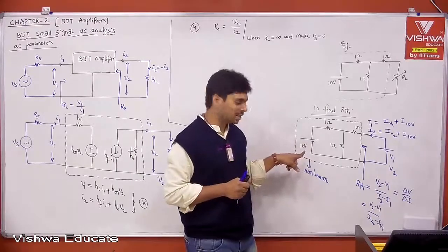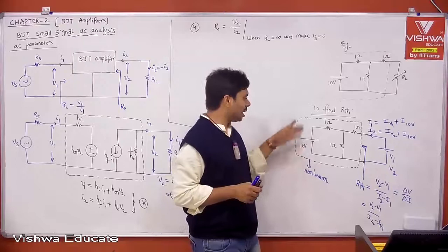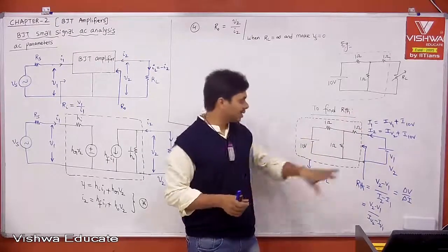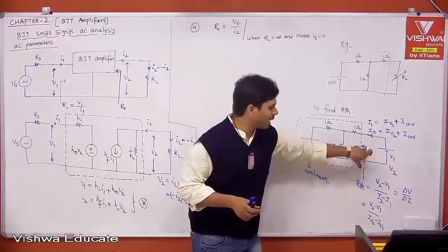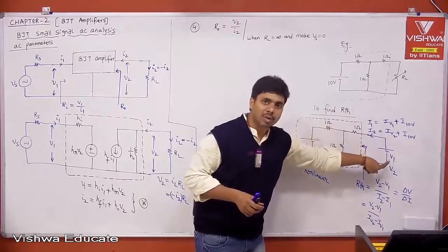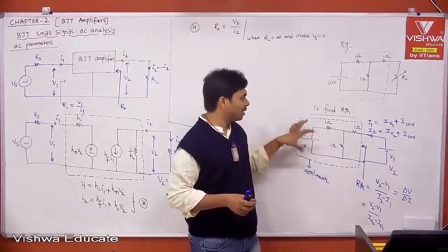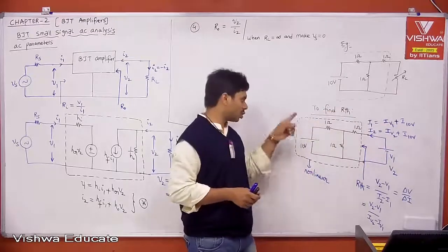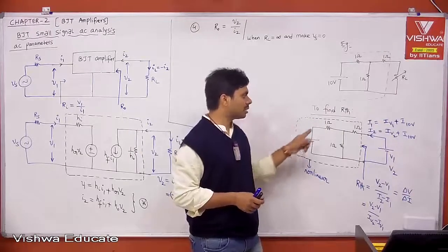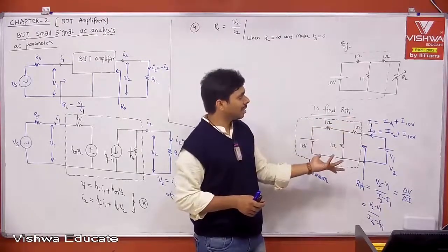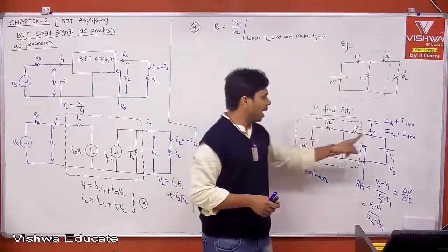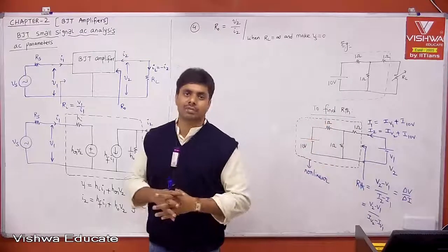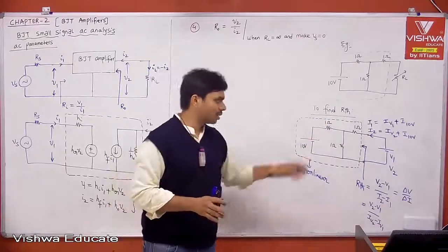During AC analysis, we don't need any common quantity; you can replace it. Therefore, straightforwardly we can do it, because ultimately I want the AC resistance or Thevenin's resistance. Therefore, I want the output current only because of the output voltage. I don't want to see any internal voltages which will change my output current, not because of the output voltage. That's why we are shorting it. To not see any effect of this on the output current, we can directly go ahead and short it, apply a simple voltage V1 by A1, and that will give you the answer. That is your R Thevenin, following the methodology of shorting it.